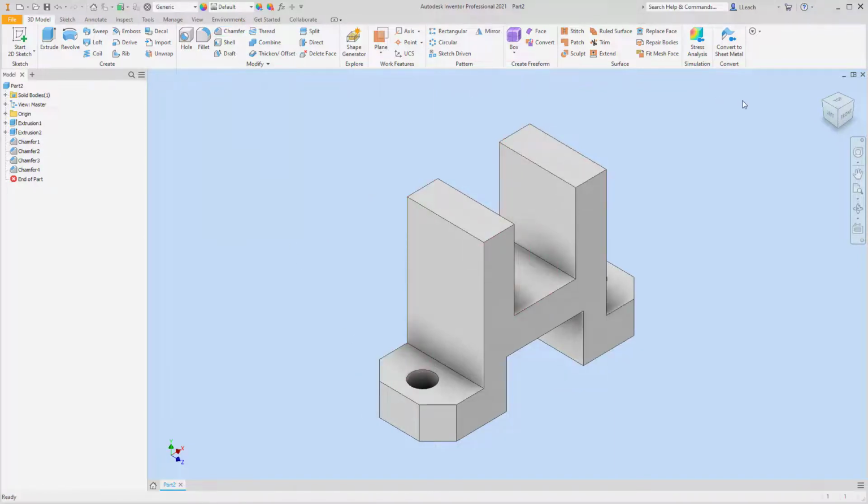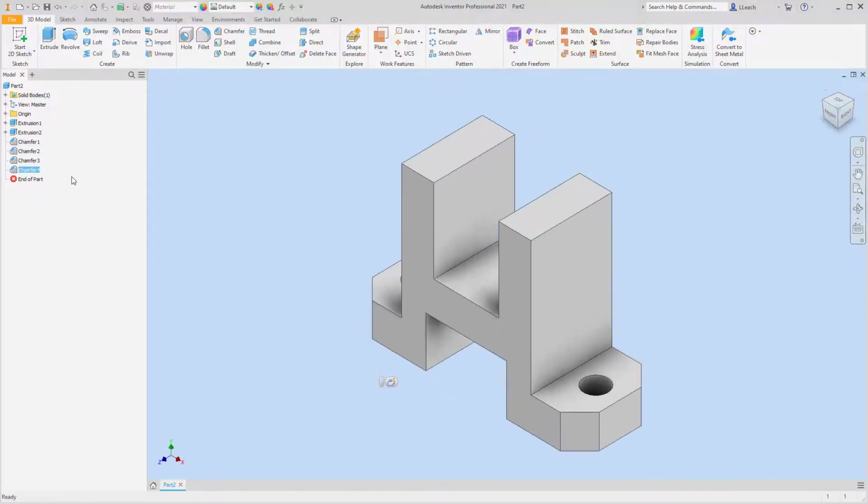So that's kind of how to do, oh wait, you know what? I didn't need to chamfer the 2 back edges. So let me go back to my original view. I'm gonna go where you see the chamfer 4, right click it, and delete that one. For 2, I'm gonna right click it and delete that one too. All right, so I didn't need to do all 4. I got a little over exuberant. So just these first 2 in the front.